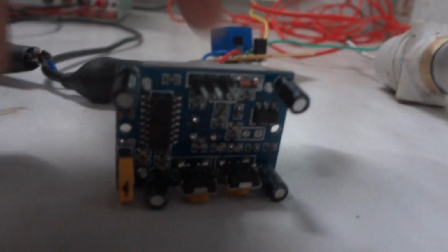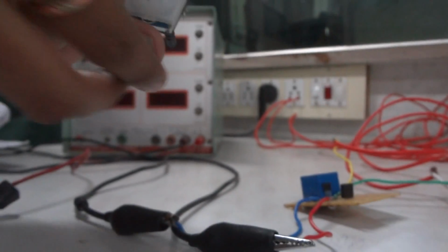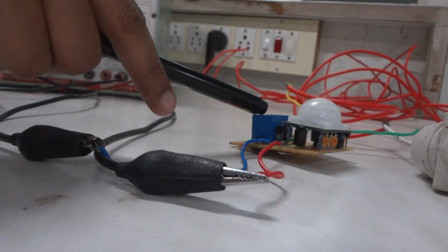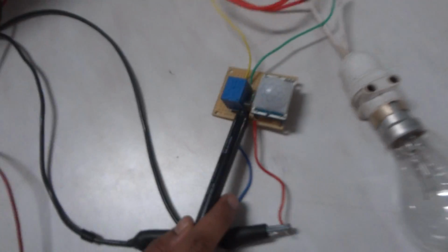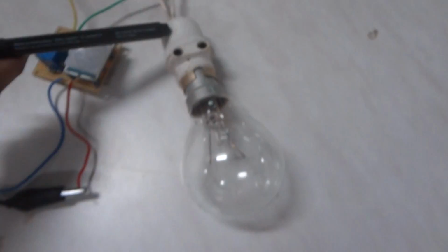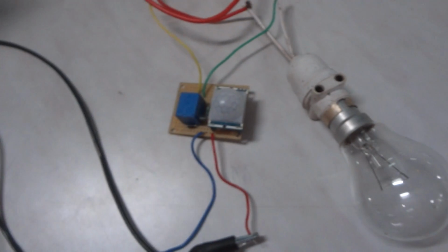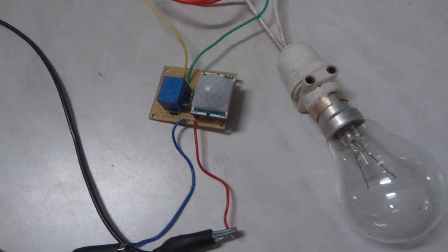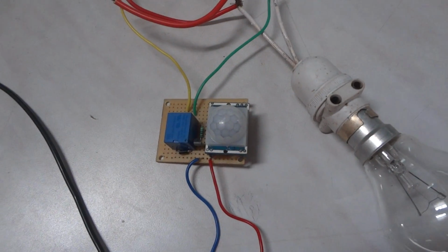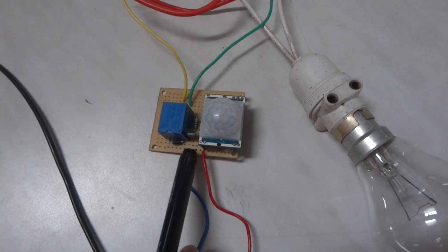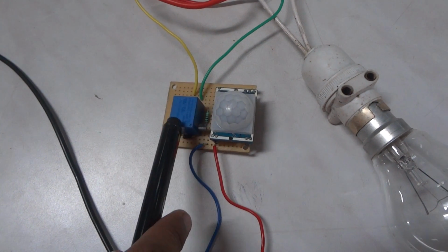Now, our circuit contains a PIR sensor, relay, transistor BC547, a freewheeling diode, power supply, and bulb. Working of each component. Transistor: it is used as a switch. When the output of the PIR becomes high, it produces sufficient voltage to make the transistor on. It energizes the coil of the relay.